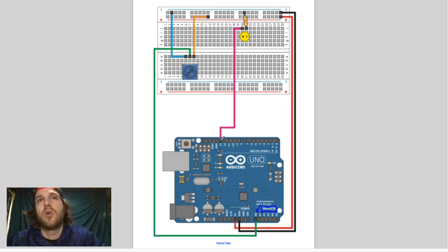Okay, so we have coming out of port 13. You could choose any port here. The positive side of the circuit, it's coming out here. It goes to the positive side of our LED, up through the LED, down to the negative pin. It goes back here. It hits the resistor, which goes back to ground. If you don't have this resistor present, then this will be receiving too much electricity and will get burned up. So you got to protect it. And really 330 ohms is what we're using to protect LEDs on 5 volts.